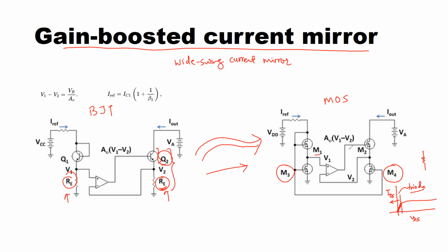And then M1 and M2 are operating in their active mode, same as Q1 and Q2 here. And the rest of the circuit will work just fine, as you see with the BJT mode of operation. And the minimum compliance voltage right here would also be the VDS plus the voltage drop across M4 and M3 operating as resistors. So that's your minimum voltage, okay?